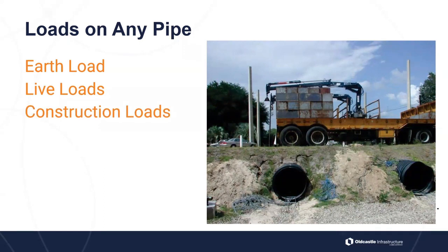We've also got construction loads. When we design our pipes, whether for concrete pipe or flexible pipe, we're not always taking into account the construction loads. A lot of times the construction loads can be much higher than any of the live loads that we may see after construction. But we need to keep those in mind as well.